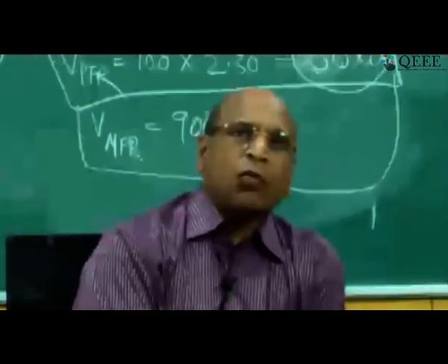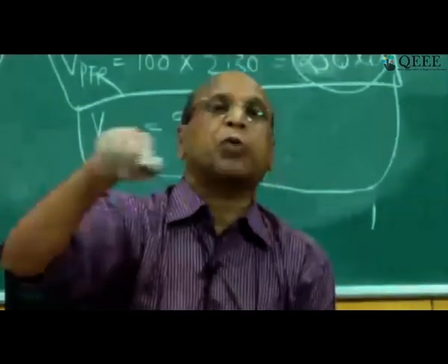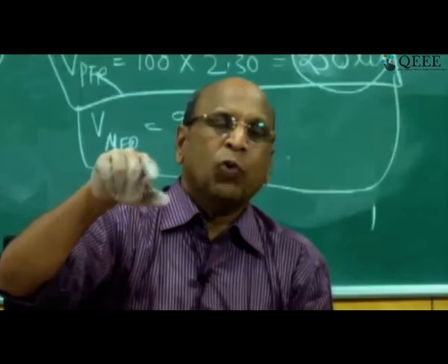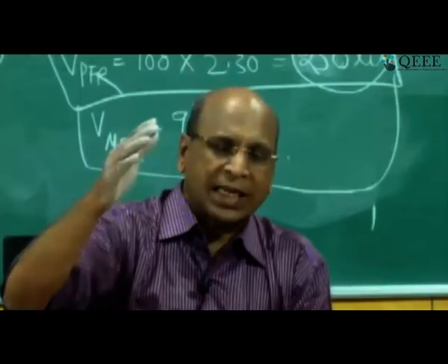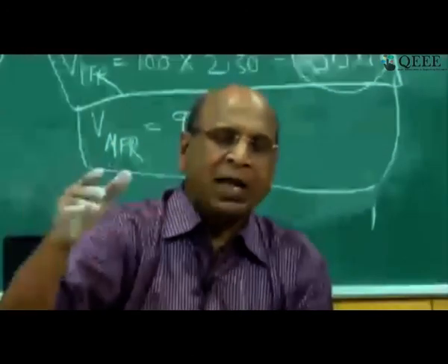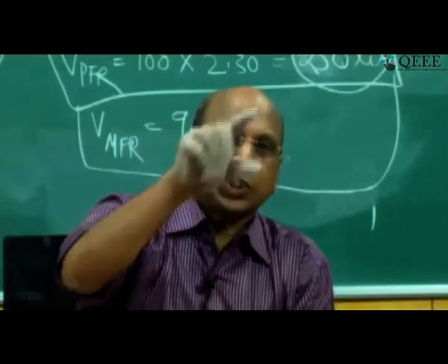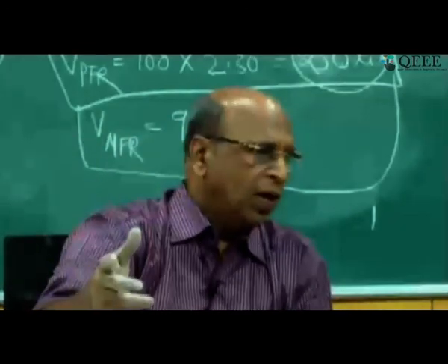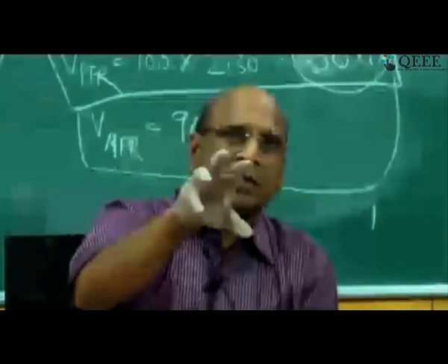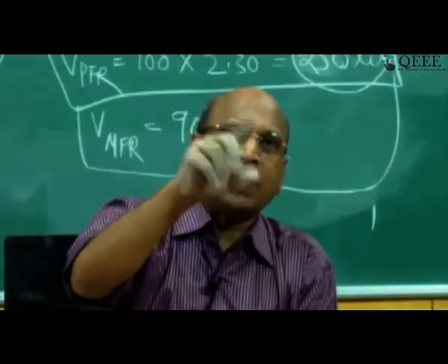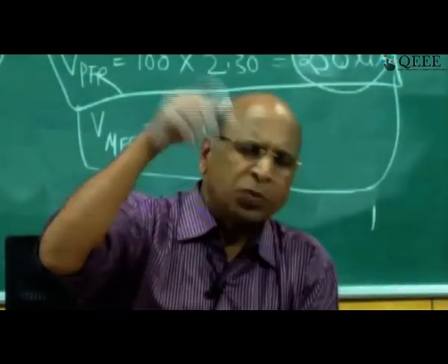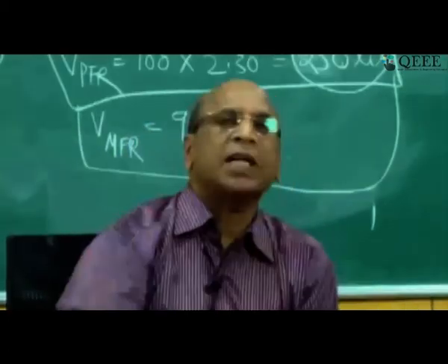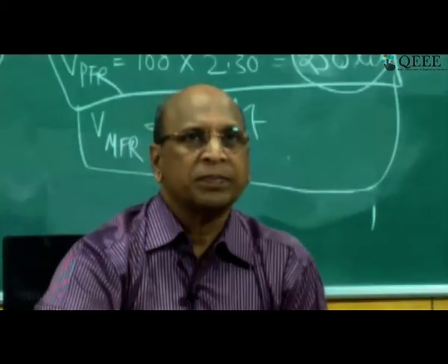From the tracer method, what you find is the residence time distribution. We find out how the tracer concentration varies with time, and then find the distribution. By plotting you will know, and using that information, by finding the first moment, the mean, you can find out the residence time in the reactor.